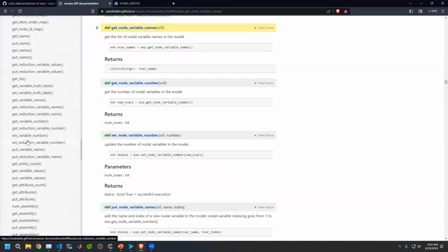What we'll use this for in our DAKOTA study is that when we run our simulations, we have Exodus files as output. We're actually just going to use this Exodus module to grab the nodal variables, like the nodal displacement at the node that we care about. You can use this also for post-processing. So if there's any graduate students in here as well, this also makes Exodus a pretty enticing option for writing your graduate finite element codes with.